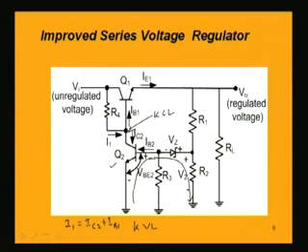So lesser base current IB1 means in the transistor Q1 the emitter current IE1 flowing from the transistor Q1 is also lesser. So finally we get IE1 less, meaning the load current which flows through the resistance RL will be less. So V0 will now be less. So the effect of the increase of V1 will finally be reducing or decreasing V0. That means it will be kept constant, or maintained at a constant value.